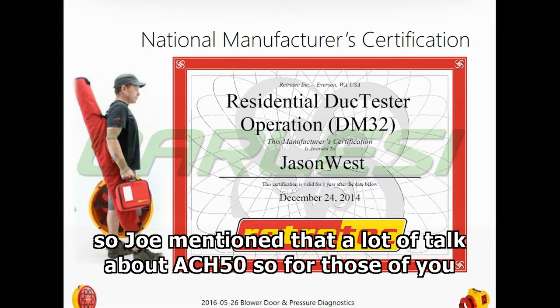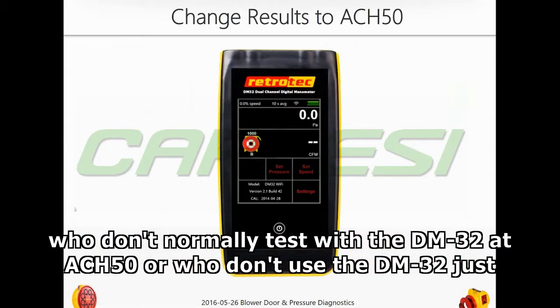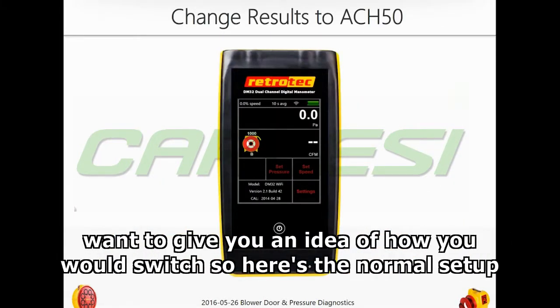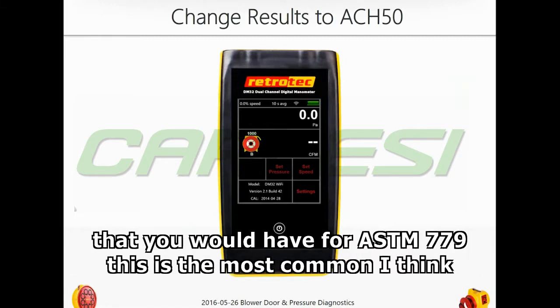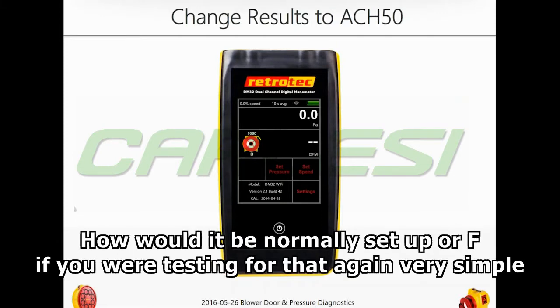So Joe mentioned a lot of talk about ACH 50. For those of you who don't normally test with the DM32 at ACH 50, or who don't use the DM32, I just want to give you an idea of how you would switch. So here's the normal setup that you would have for an ASTM 779 test. This is the most common test in the United States. It's 50 pascals, testing for CFM at 50. So this is how it would normally be set up.